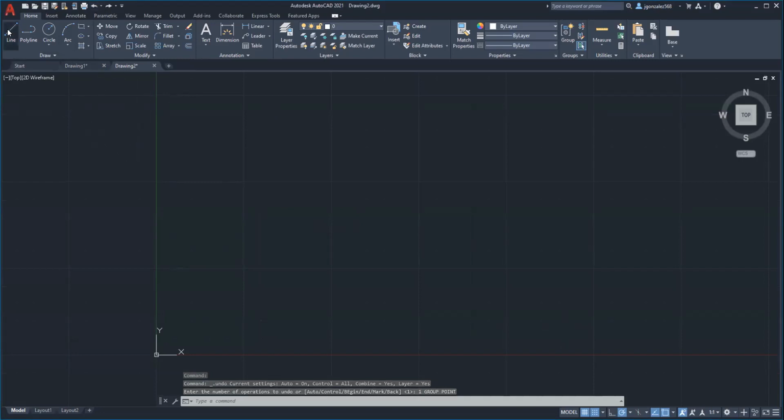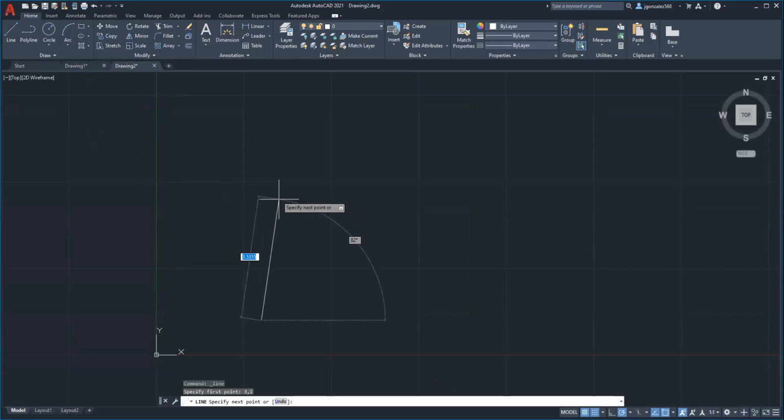So using only the line command, I want you to select exactly where you want the corner to be. So the first point, you can just simply type it in. So it's 3,1, enter, and it does the first point. But notice how now it's asking how long this line is going to be, at what angle, etc.